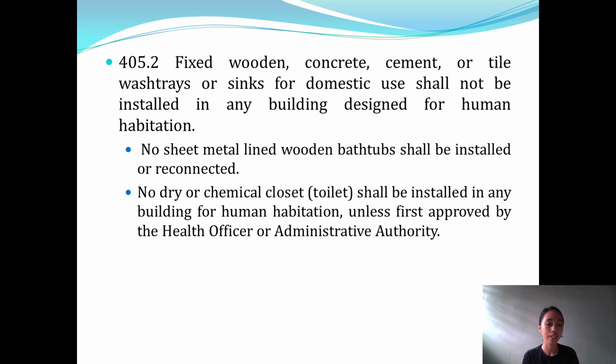The wooden fixture is prohibited because of its tendency to become insanitary. It is not impervious or smooth and cannot be fully cleaned with its use. The dry or chemical toilet should only be used if no other means exist to provide facilities for the occupants of the facility. They should only be used if the health officer approves. Usually, a local health department inspector approves its use.